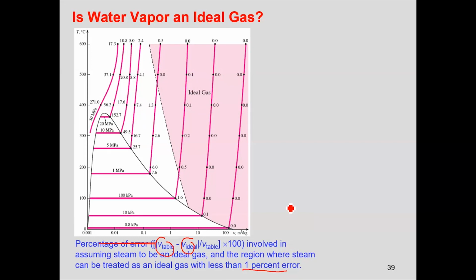So this is already done for water vapors. But in case of a refrigerant, you don't know what is the error that you will have for a specific pressure. If your pressure is 0.094 megapascal or 94 kilopascal, what is the error that you'll have using the ideal gas equation and the tables? If water has an error of 1% at 10 kilopascal, I suppose 94 kilopascal is not a good enough pressure to use.